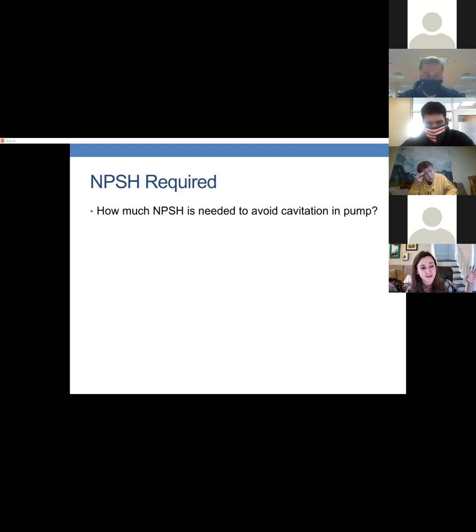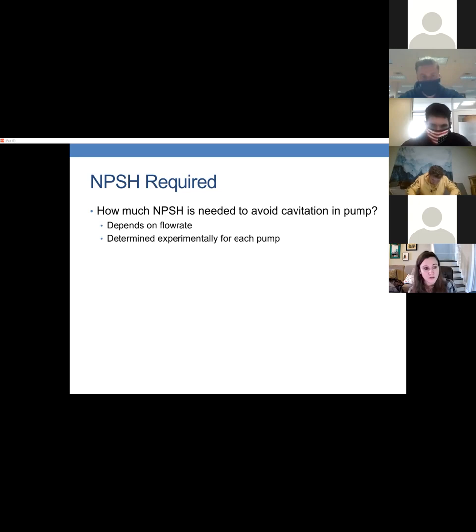So that'll mean there's no cavitation in the pipe leading up to the pump. If NPSH available is positive, then inside the pump, its pressure might drop some more. We don't know. And so we need some buffer. You need some buffer head. And how much buffer head do we need? It depends on the pump. Okay? And it also depends on the flow rate.